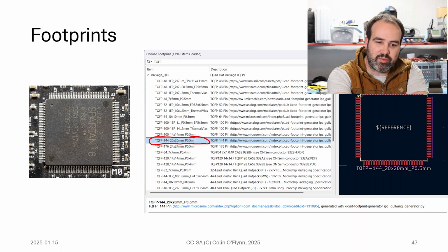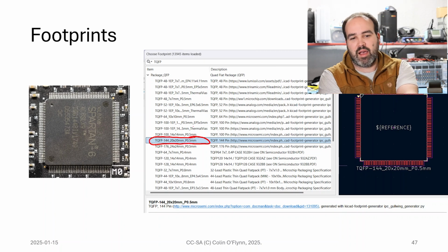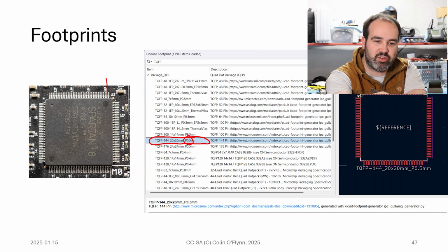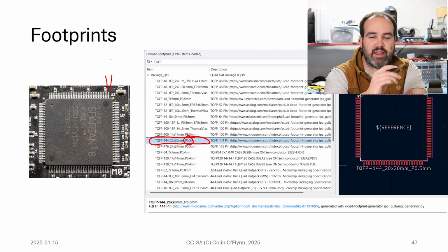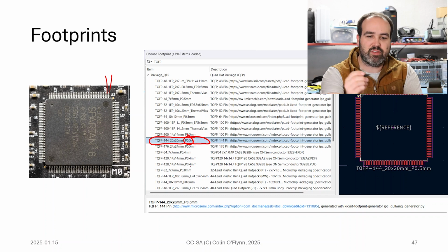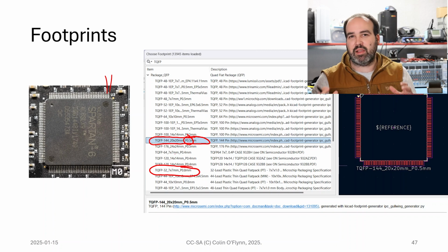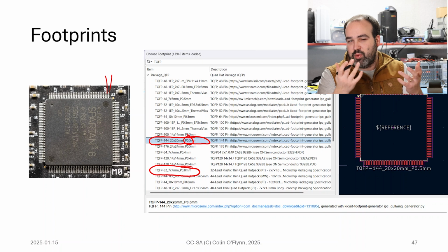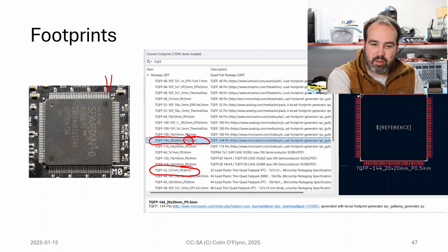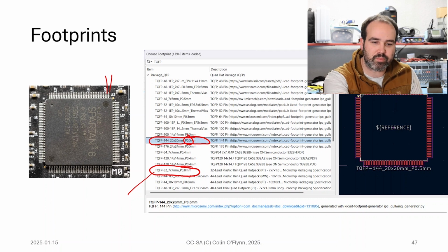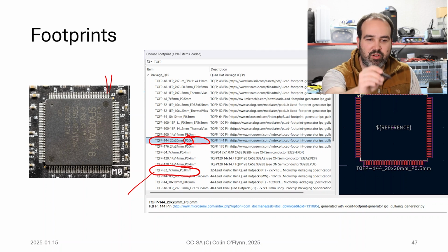So this is like a TQFP, this is an FPGA. This one you didn't have too much choice, but you had this 0.5 millimeter pitch, which is the distance between the pads. The bigger the pitch, the easier it's going to be to solder and work with for prototyping, right? So if I'm looking at something like an AVR, like the Arduino microcontroller, I could actually pick a 0.8 millimeter package. They have a bunch of devices in that package. They do have devices in smaller packages because I might want a smaller package, but that's going to be harder to solder. So watch out when you're selecting packages.